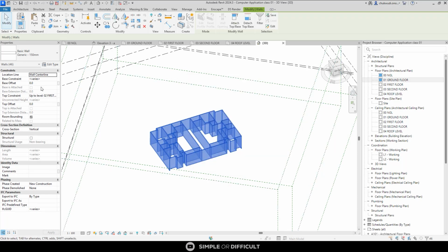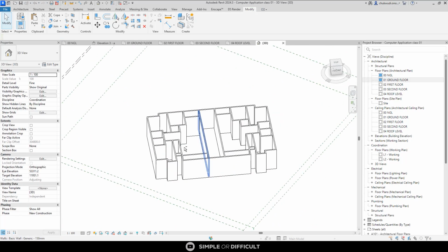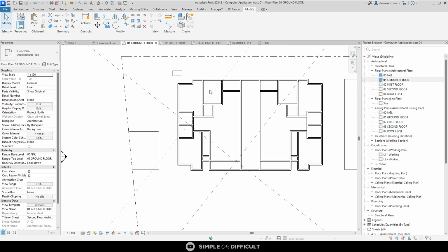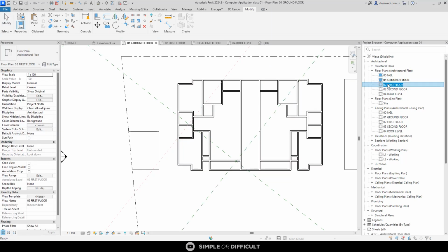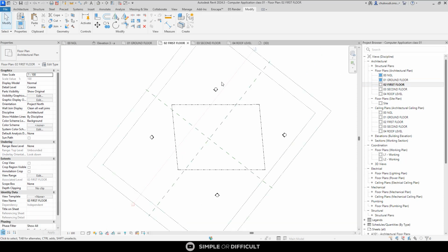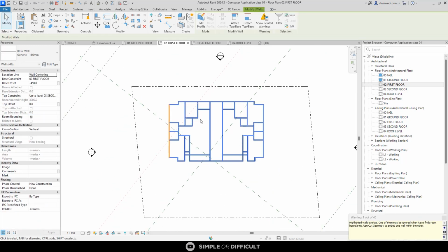So with all the walls selected, I'm going to make sure that all the base starts from the NGL and then all the top ends at the first floor. And that is what I've done now. And that is what it is. So I'm going to come over here, select this, copy this, and then drop this down. Okay, before I do that, it is going to be longer than normal because I added the NGL to it. So I'll just come over here and then paste it in place. Okay, I'm going to paste align to current view. Now, when I do that, I am going to minus 450. I'll put that minus 450. I'll change it to 0, what I've just done now. Okay, and that has solved it.